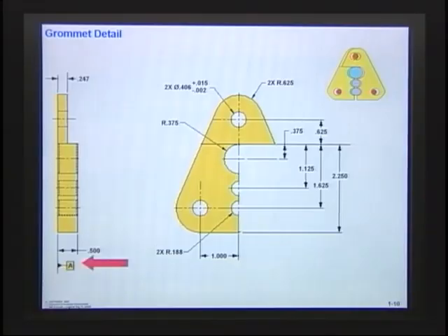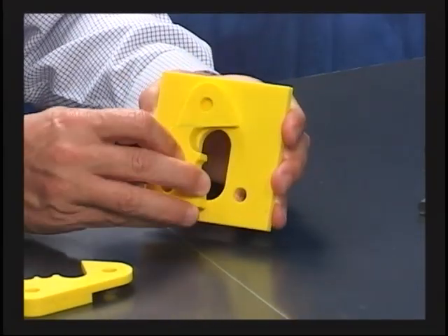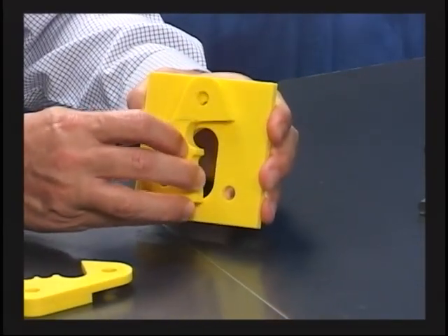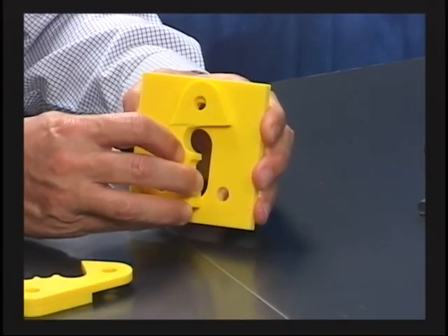All right, I'm back. Here I am. I hope that you've had a chance to apply the datums. That's the first step, remember, in establishing the datum reference frame. So number one, this is what I did: I established that face as datum A. The reason is, if you take a look at my models, this part matches up to the bulkhead and mounts tight up against that face. If it mounts tight up against that face, I saw that as the primary datum.